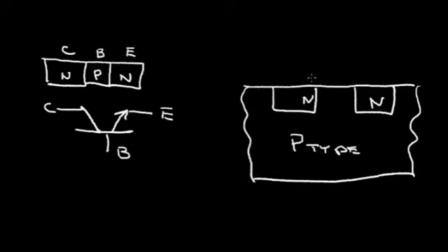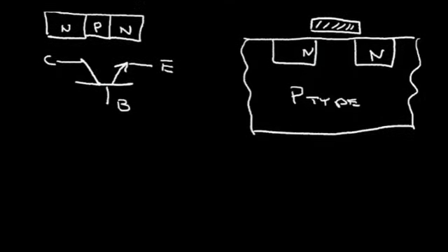If we put an insulating layer above this center region and put a conducting region here, we form what we call a MOSFET transistor. And its symbol is like this. Because this region is N material, we call this an Nmos transistor.